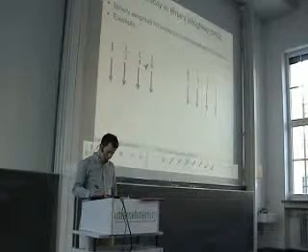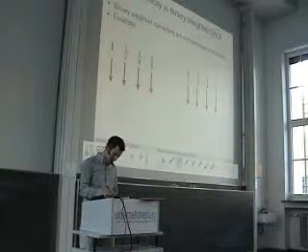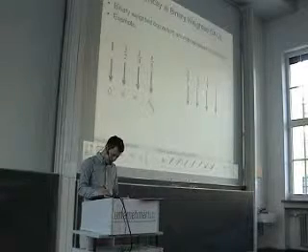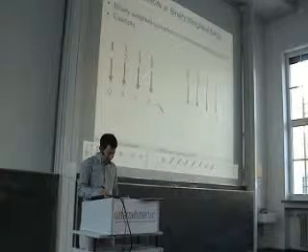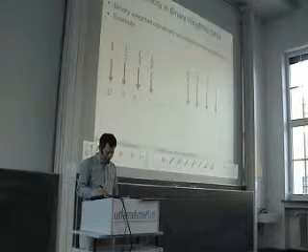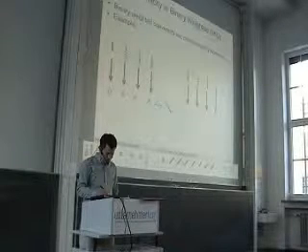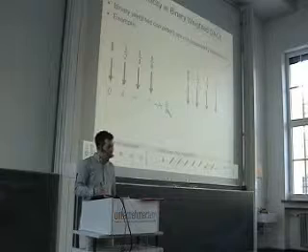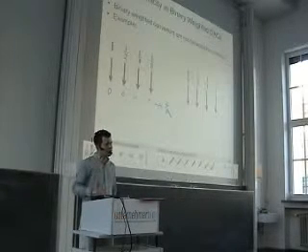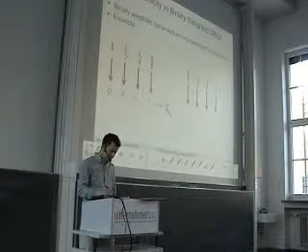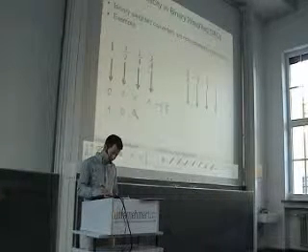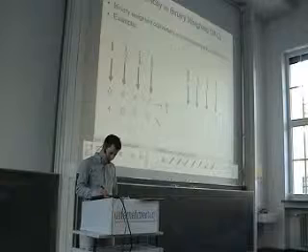So let's assume that we have a first input word which is 0, 1, 1, 1, and this would result in an output of 7/8, and then we increment this by 1 LSB, so we have 1, 0, 0, 0, and this leads to 1.